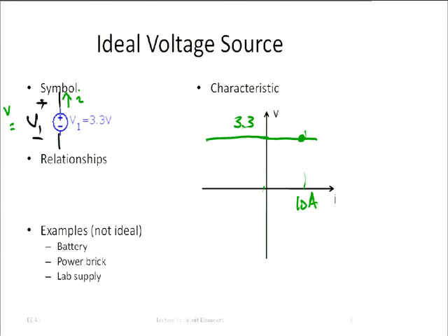And we are in this point now. What's the power that this source is delivering to the rest of the circuit? Yeah, minus 33 watts, right? So again, be very careful. This was nothing new. That's what I told you on the previous slide that you know by now. Sign conventions tell us that the power delivered, that's active sign convention, is simply the voltage times the current.